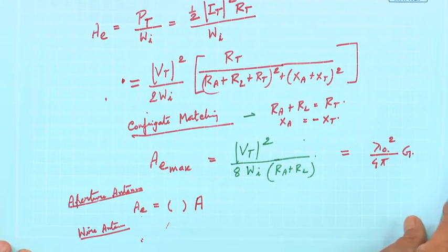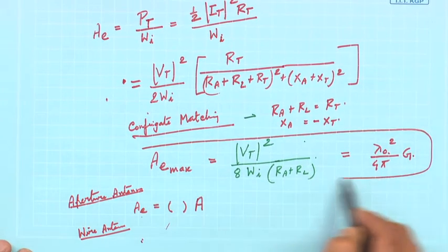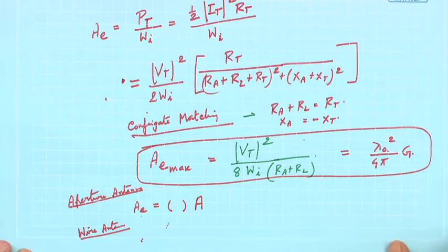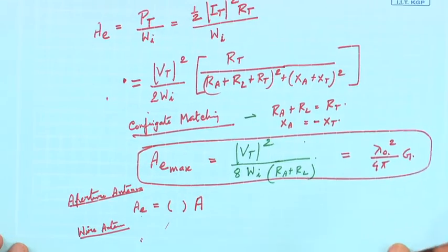Now, let us go to prove that point. This is a very important relation, various times we will use this in most of the models of communication, radar, etc. This formula is used, but to prove this we need to find out one thing. This effective area concept we have introduced. When we introduced the current element at the start of the lectures, we found some antenna parameters of the current element, but we did not find its effective area.